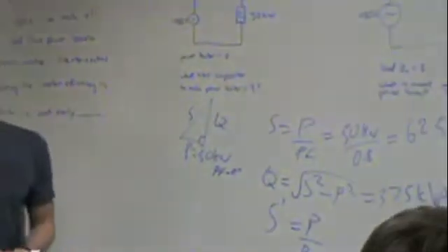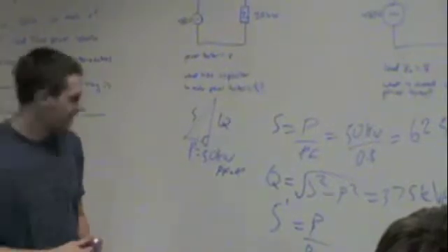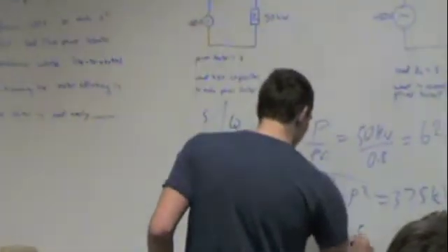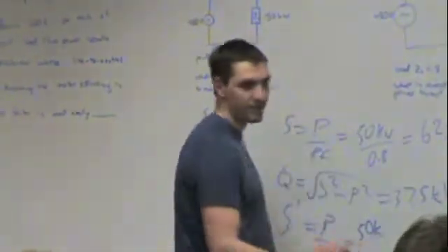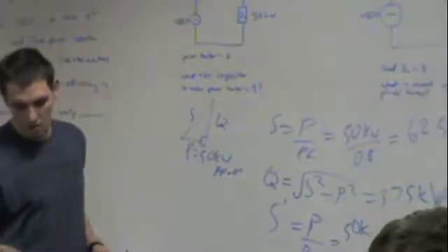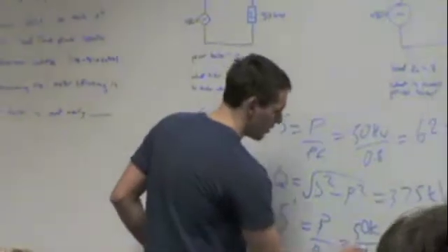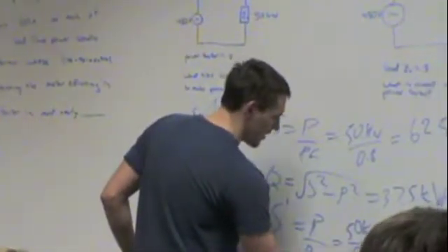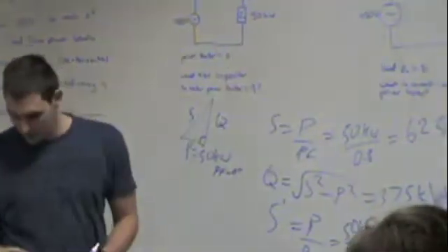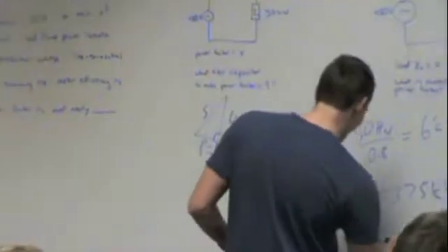Because I love to hear that I'm right. And then we are going to say that this is 50K, because we know it's the same, because capacitors add no real power. And then we're going to do the power factor, which is 0.9, and then we get 58.